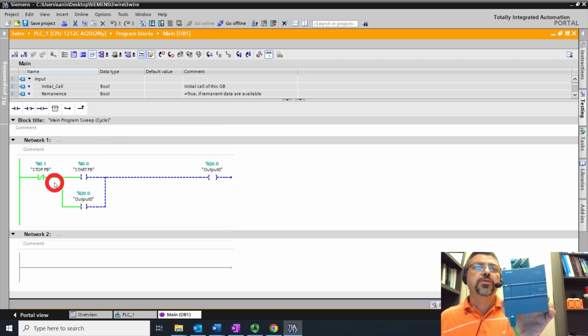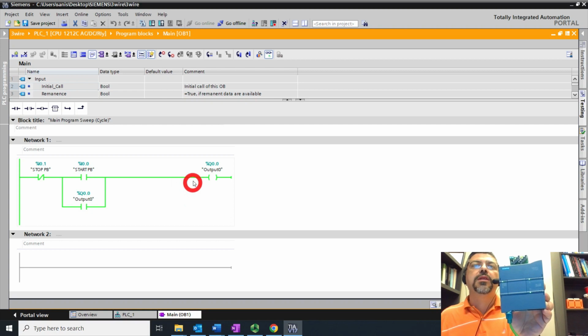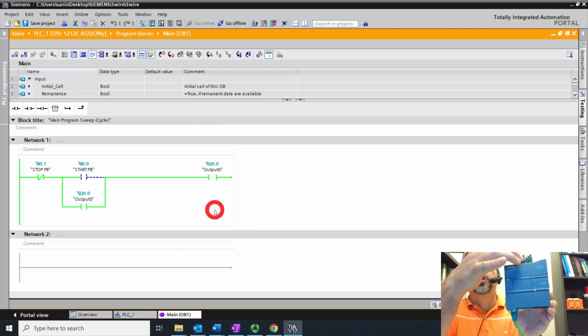Whenever it is 0, it is normally closed. It's closed, so you have the power here, right? You didn't push the start button, so it is open, but whenever you give it a 1, it should close and be able to start. So this is my start button, the first one. I turn that on, so that means the motor is now working, and see, even if I release the start button, the motor is still on because of this element that we put in the ladder logic. If you want to turn it off, you just go to the stop. You stop it, everything is stopped.